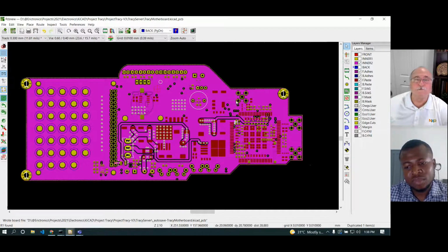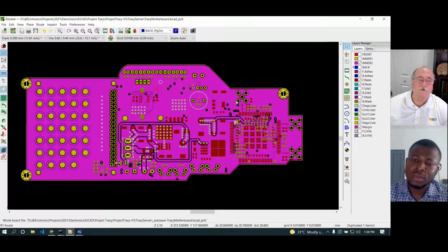And then the flooding of ground everywhere. If you don't need to route a signal, then you put ground there because that helps keep the energy that you're trying to control, the signals or the powers, those electromagnetic fields will stay close to where you want them to be, in the space between the routed conductor, or what I call the switched conductor, and the unbroken conductor or ground. This has become a very solid platform for this circuit board.